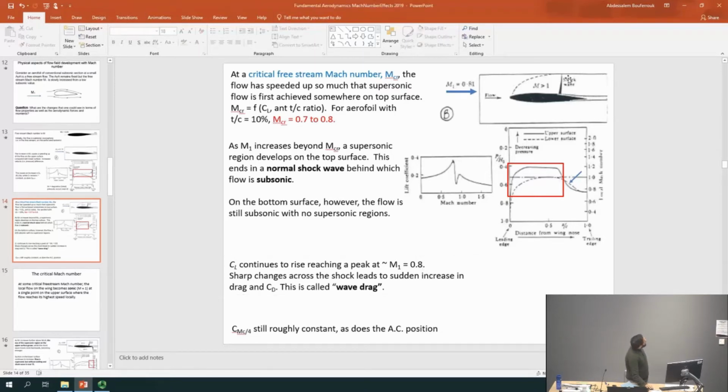And of course, because we have the shock wave, the first thing you need to think about is that you must have what we call wave drag. So suddenly the wing is kind of struggling. The wave drag, once you have the shock waves, is appearing there. So we can't ignore it. Remember I told you before the drag is slowly not increasing, but now we have the shock wave, definitely there will be an increase in drag. That's called the wave drag.